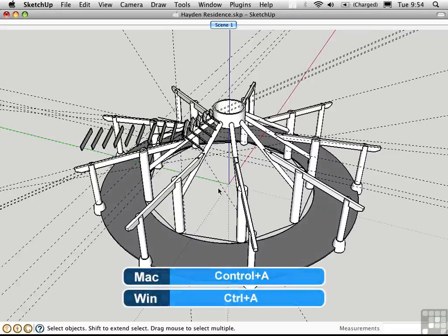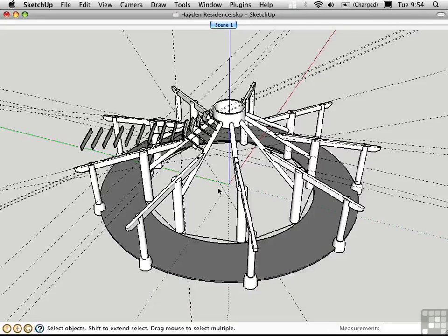There are a couple of different ways to change the axes. In the first approach, we'll use numbers, and then I'll show you how to do it graphically. Let's say we know a specific angle that we'd like to rotate the axes. This will allow us to draw geometry on an angle. Right now, if I were to draw a rectangle, it would align with the axes. Let's go ahead and change the axes and draw another rectangle and see the difference.